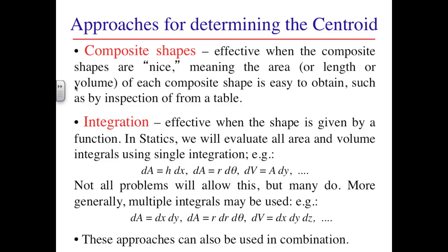I am frequently asked if I expect you to memorize these tabulated quantities. Absolutely not. The only non-symmetric shape you should commit to memory is the triangle centroid. In the case of a triangle, the centroid is 1/3 of the height from its base, or 2/3 of the height from its apex. The reason for committing this particular result to memory is that we can consider many distributed loads as a superposition of uniform load, which it will turn out will look like a rectangular shape, and a linearly increasing load, which looks like a triangular shape.